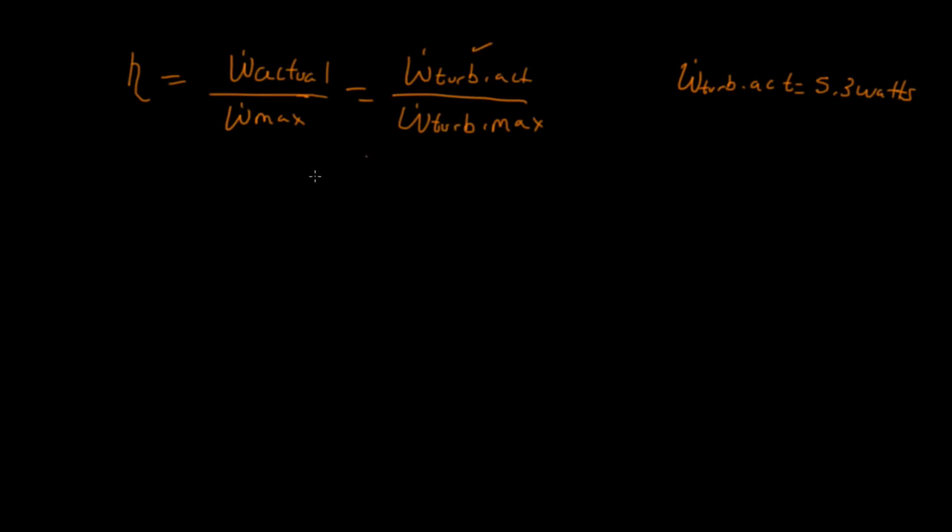In order to do that, we are going to use fluid mechanics. So let me go ahead and write down the energy equation. The energy equation is kind of long, but it is mass flow rate times pressure 1 over density 1 plus velocity 1 squared over 2 plus the gravitational constant times the elevation 1 plus work of any pumps in the system.